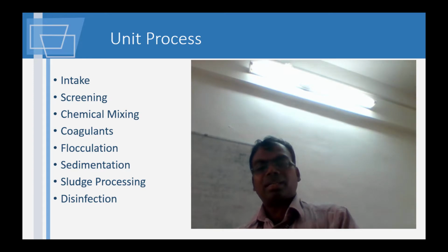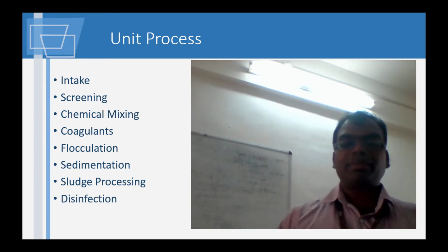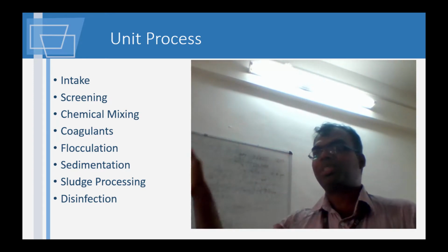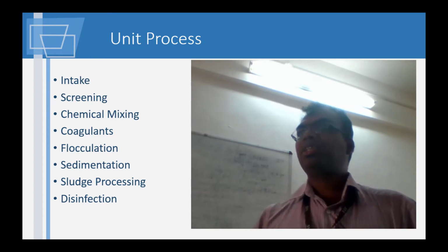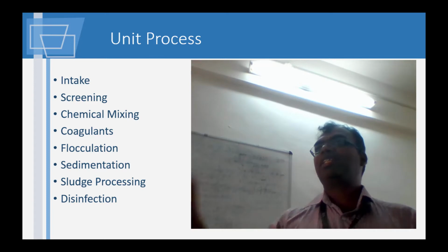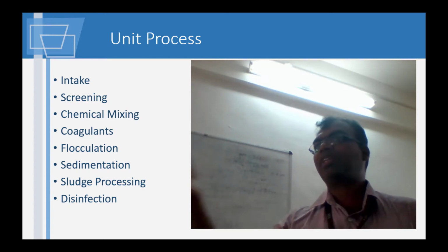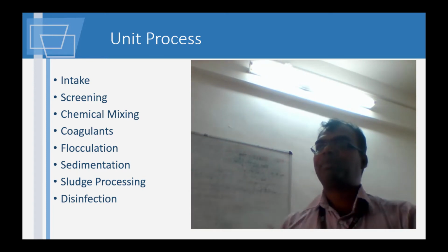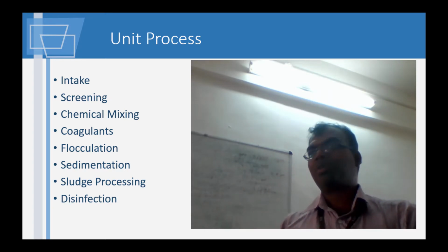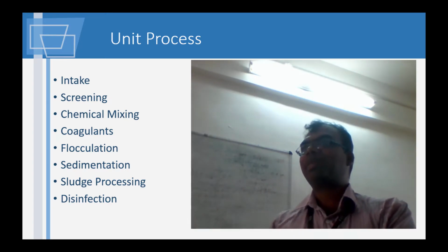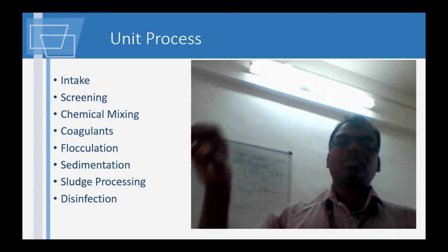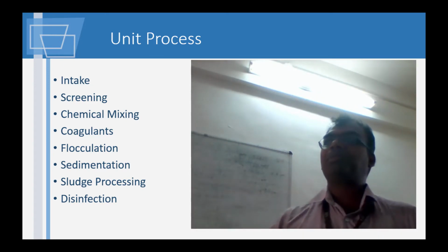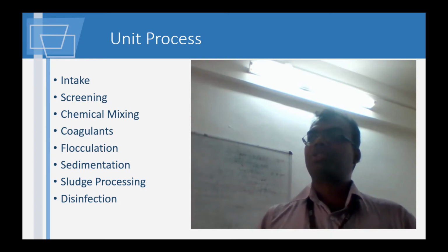Okay. So then another thing which we have not come across: sedimentation, flocculation, coagulation, we have seen quite a lot of videos. Sludge processing is something which we have not seen at all. What is this sludge? You are getting these flocs and everything. All these are very fine colloidal particles which have been made bigger. They are still small only, just that they are held in place by that positive charge which is there in that coagulant. So this will be a very big problem to dispose.